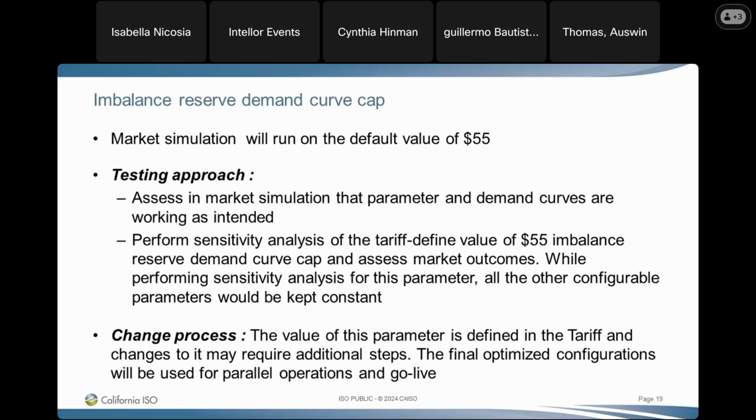And of course, those attenuation factors are a forecast that's liable to not be correct. I just wanted to confirm that in spite of that, the storage constraints imposed on the procurement of imbalance reserves don't have any effect in real time. So if you have an award from the day-ahead market, it's not protected by any state of charge limitations in real time. The envelope constraints essentially disappear in real time. Am I correct in seeing it that way?